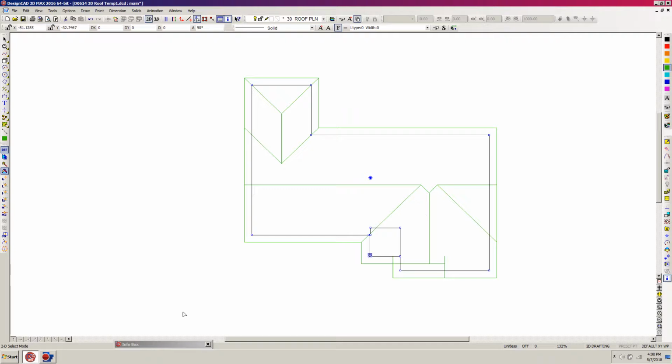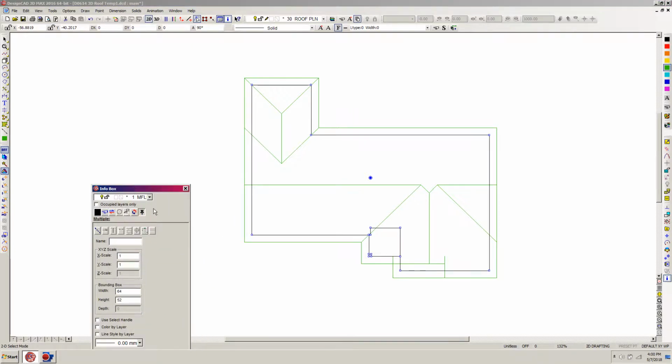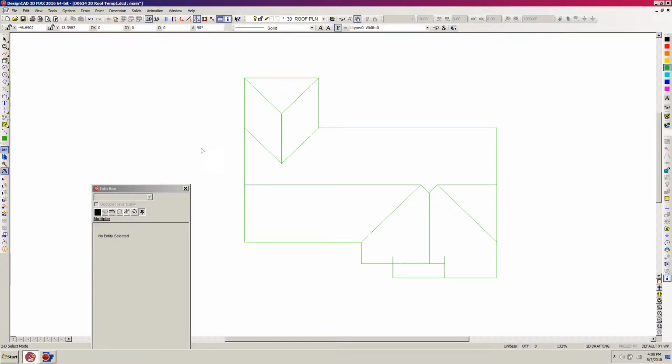You can see the existing point still. Pull up my info box, click on the layer portion of the info box, and scroll on down to 201. Oh, too far. There, and put it in that. It disappears because 201 isn't a visible layer at this point in time. Control R, and it'll show you your previous layer.